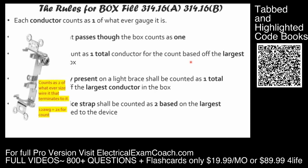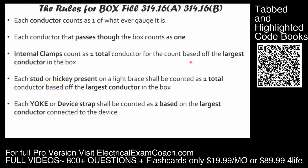As we learned earlier in the program, this is a device yoke or what we call a device strap. So each one of those, and how I like to think about it, is each gang of a box. If you have a single gang box, 2 gang box, or 3 gang box, each gang is going to count as 2 based off the largest wire that is connected to the device. So if I had a box that had 12 gauge on one switch and 14 gauge on another switch, the first switch would count as 2 12s and the second switch would count as 2 14s.